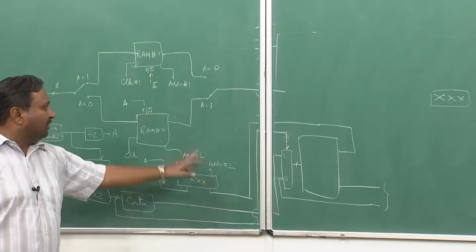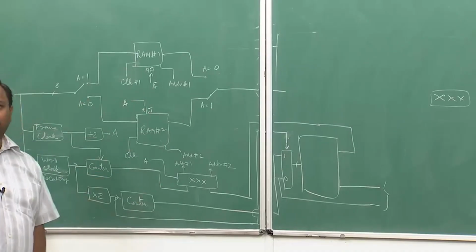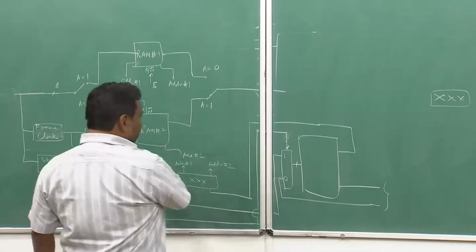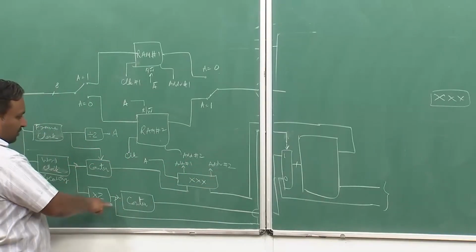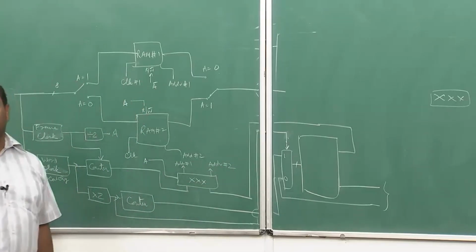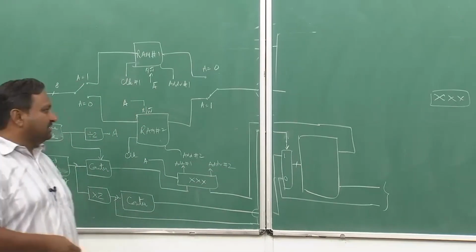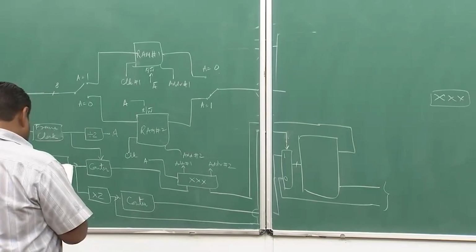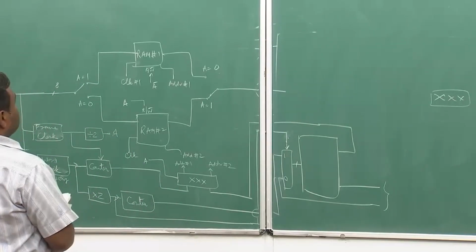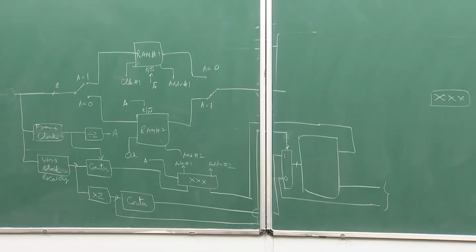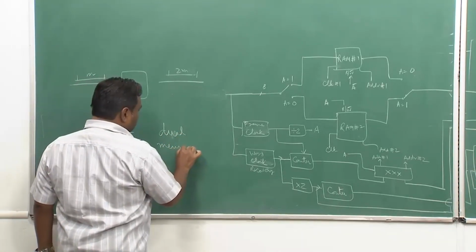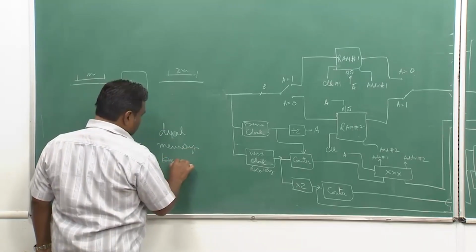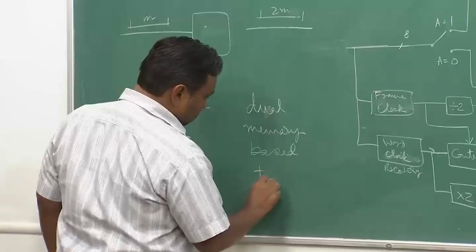So the reading signal will be going to this, or this will be decided by this particular mux, and they are now being driven by a different clock. This is the frame clock divided by 2 and this is the word clock multiplied by 2. So there is a difference here. So this is different from the earlier time switch in that sense. Okay, this I think gives the complete dual memory based time switch.